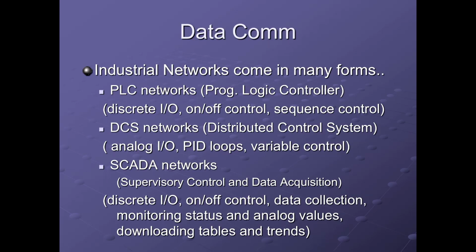When it comes to the SCADA network, and SCADA stands for Supervisory Control and Data Acquisition, there you go, there's a hint for your first quiz question to define what the acronym SCADA stands for. That's Supervisory Control and Data Acquisition. So when it comes to the SCADA network, it looks at status values within its network as discrete I/O, on-off statuses, on-off control. It looks at a few analog values of voltage, current, temperature, pressure, and data collection, like trends of a changing analog value over time loaded into a table and collected as data.